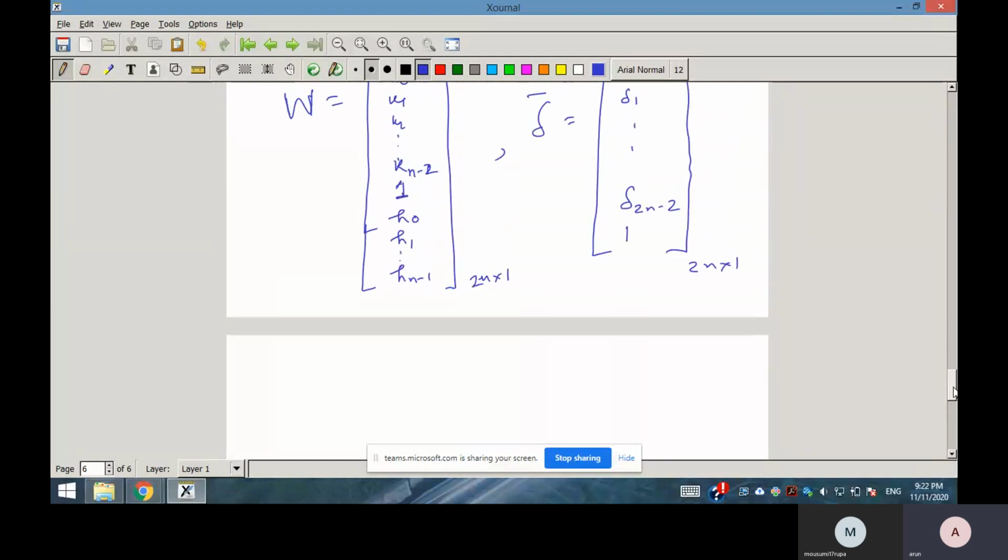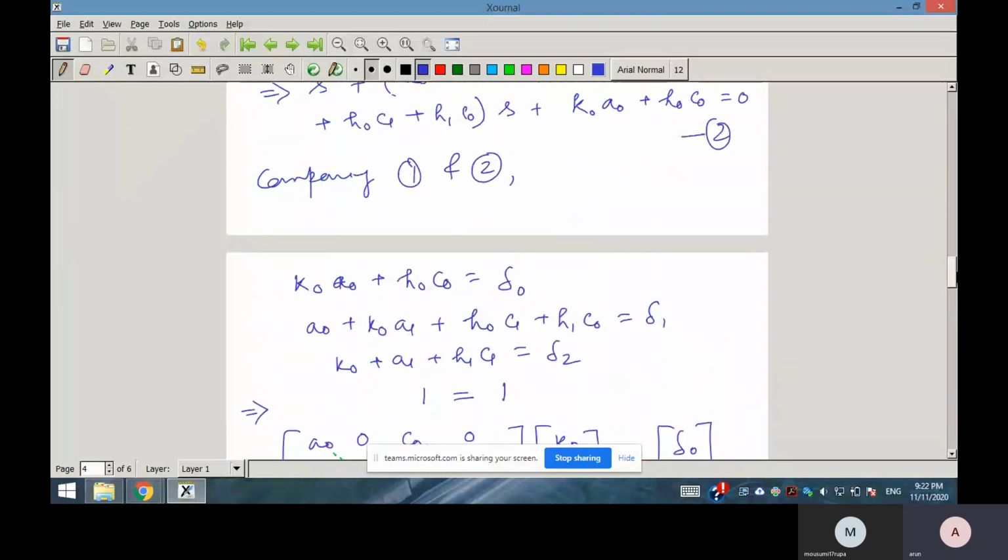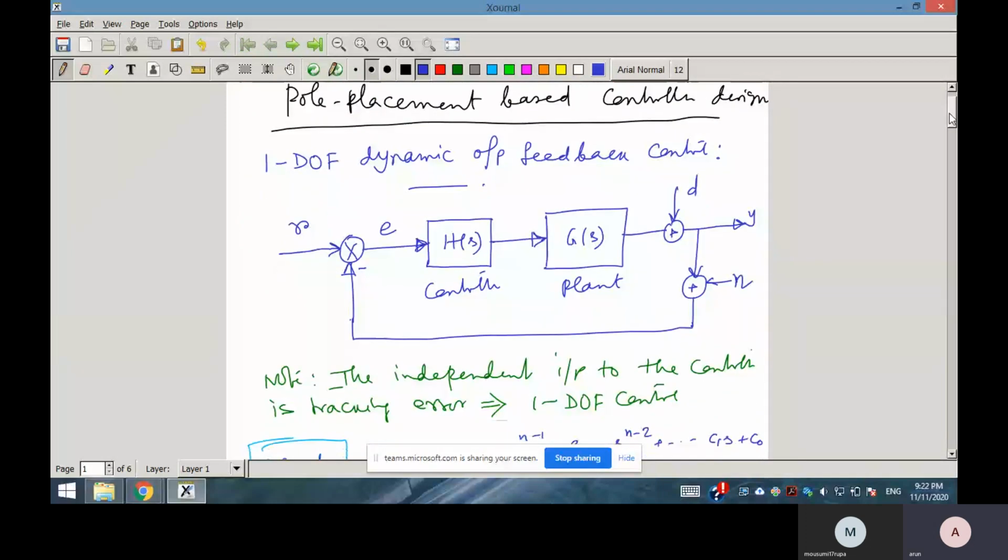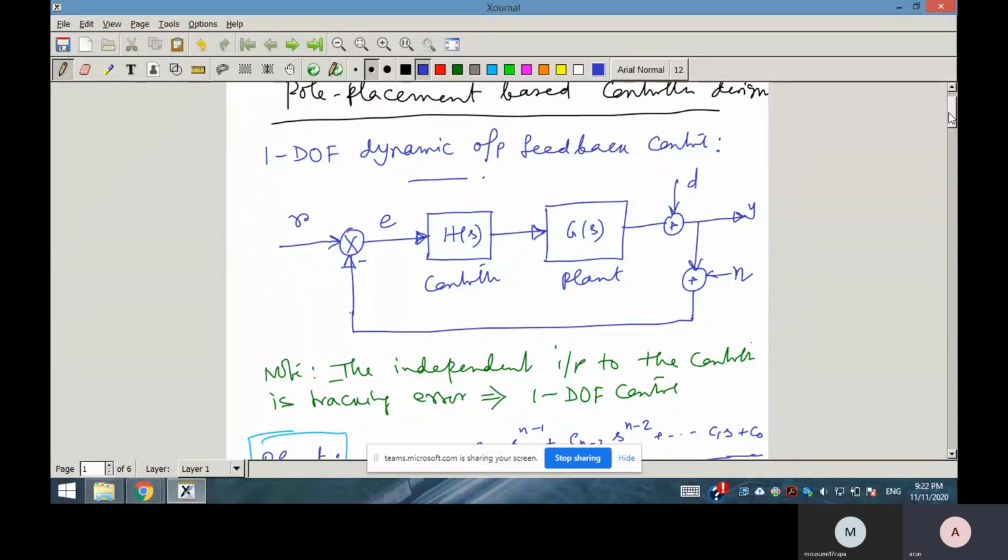Now, what are the important transfer functions that we have to bother about here? The three important transfer functions we have to bother about: y by r. This is your response. Response will depend on the y by r transfer function, and disturbance attenuation, y by d transfer function, y by eta transfer function, and overall u by r transfer function. U by r transfer function will take care of your control input. So your control input also should be within limit. Otherwise, actuator saturation and rate saturation, all those things will happen.